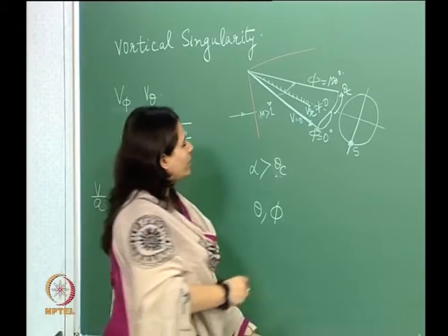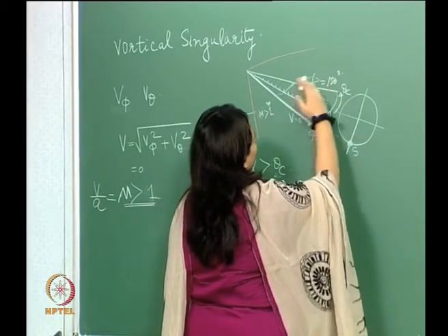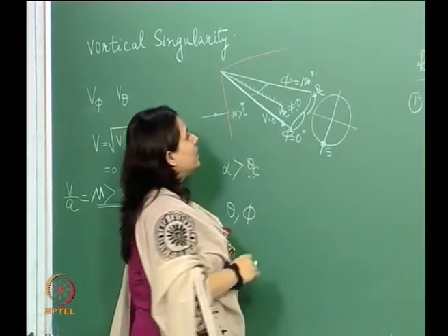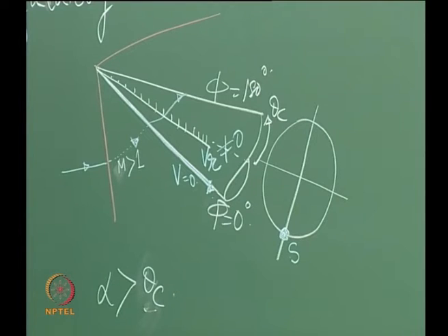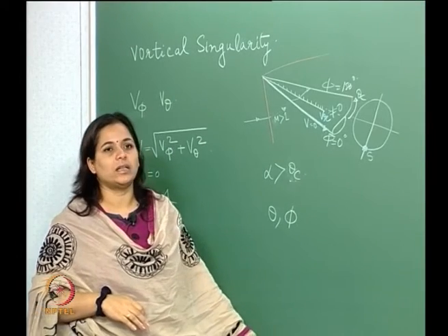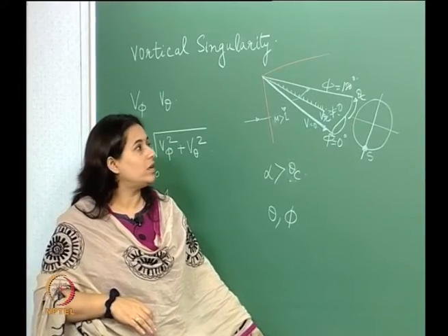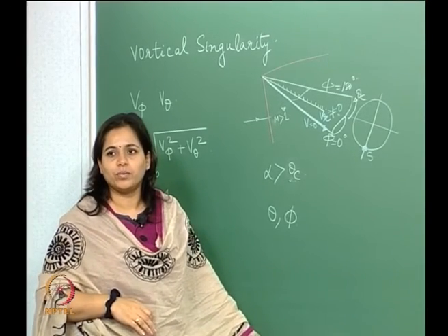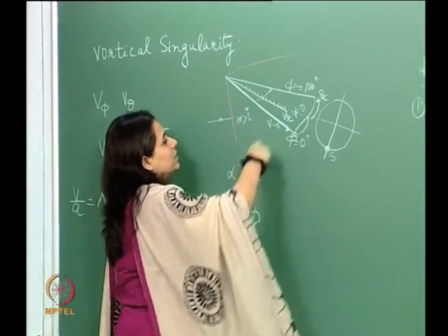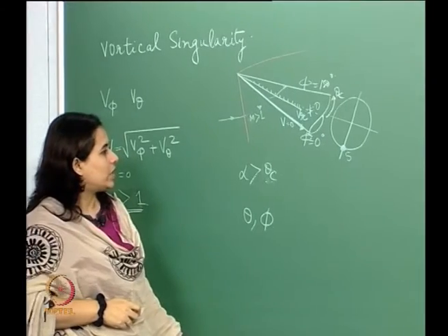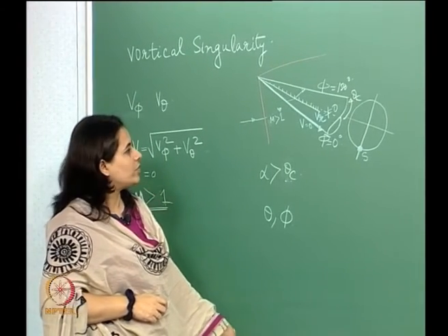However, when we come to the leeward side of it, there might be flow separation at this portion of the cone. Therefore, here an inviscid analysis may not be sufficient to predict the properties or what is going on around this region.